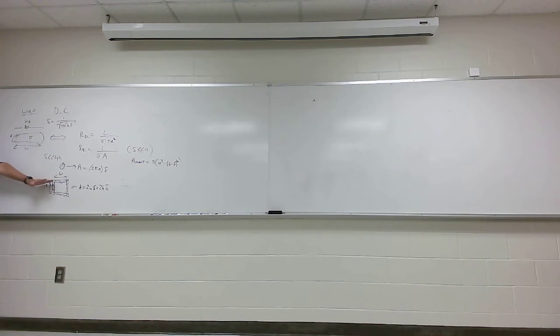I mean, you understand the principle. You go around the rim of anything, make it 1 skin depth deep. That's the area the current flows. It doesn't flow in the center. Which is why you'll see so many high frequency things, when they have connectors, have absolutely hollow centers. Has anybody observed this? Anybody work around microwave? When I did my PhD work, my master's work, it was with plasma etching materials.